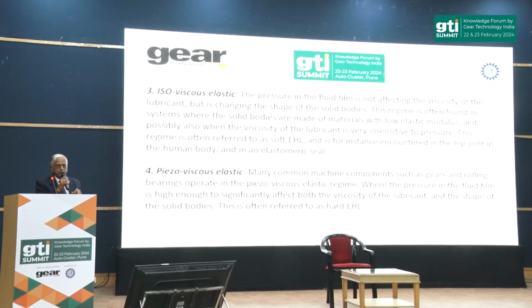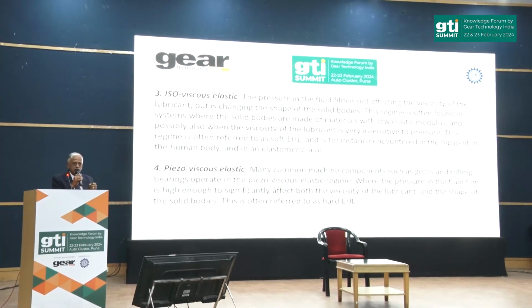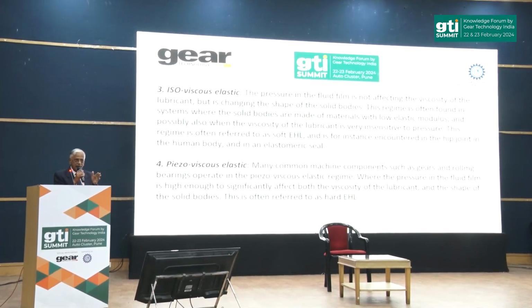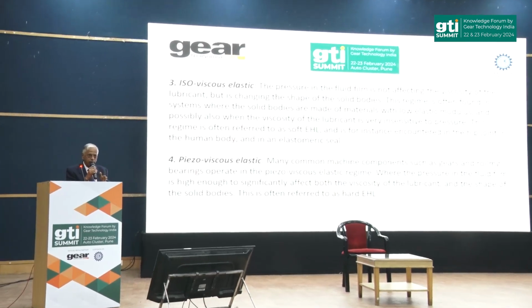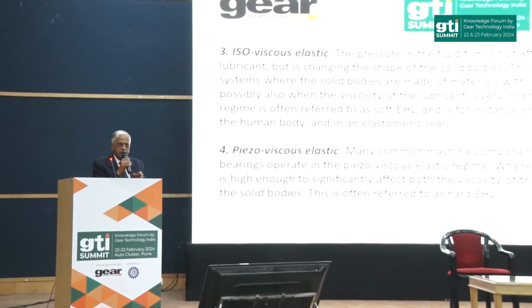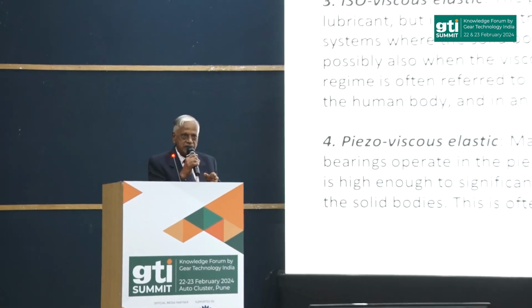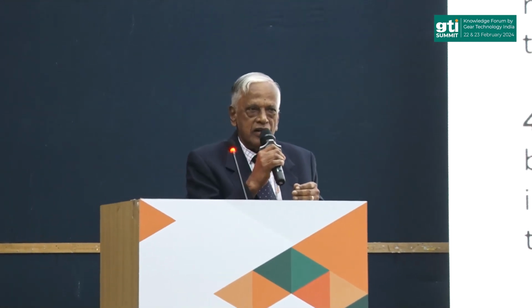So what happens is, when the load or the pressure increases on the lubricant film, it tries to resist as much as possible, because oil will not just allow itself to take the load as it is. Up to a certain level it behaves like a Newtonian fluid, whereafter it starts deteriorating as the shear ability of the oil changes with respect to applied load, and then it becomes non-linear.